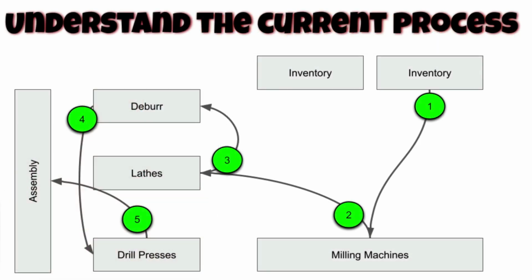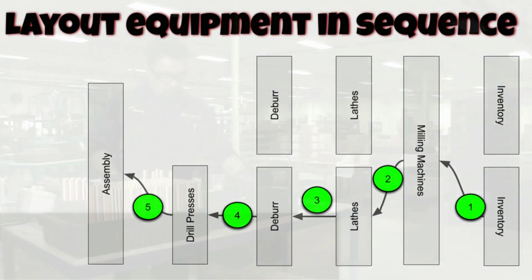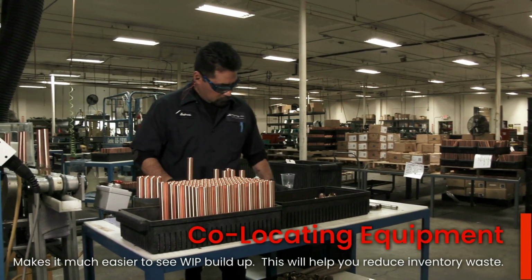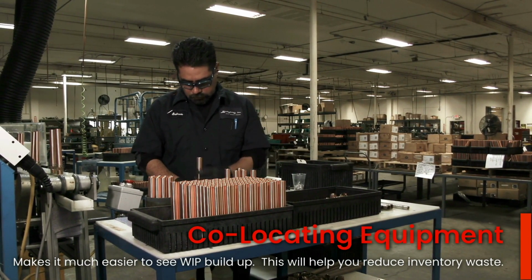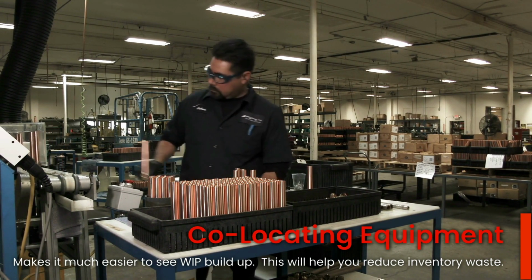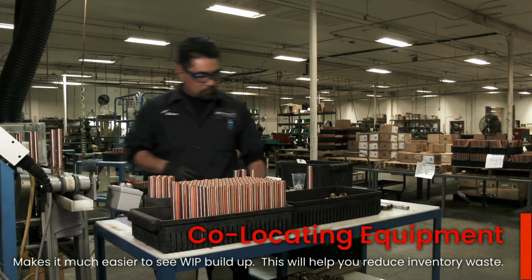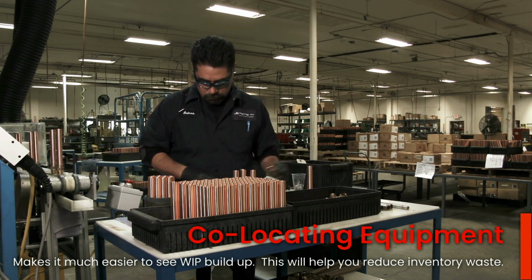Once you have moved your functional layout into a process-based layout, you will have a great reduction in the distance traveled as well as the production times. One other benefit of co-locating your equipment in a sequence is that it makes it much easier to see work in process inventory build up, which will help you remove inventory waste later on.